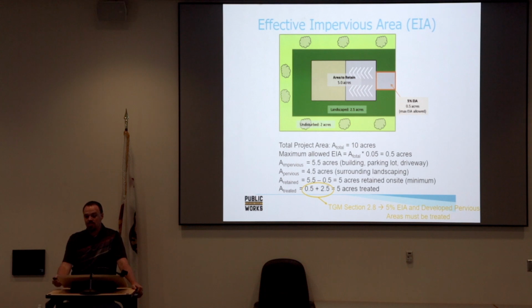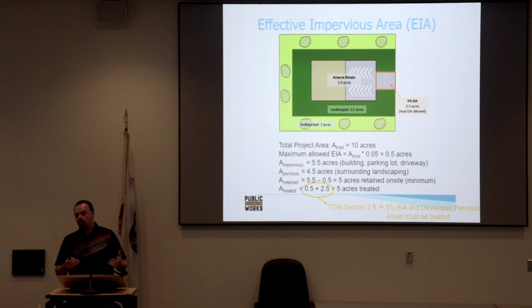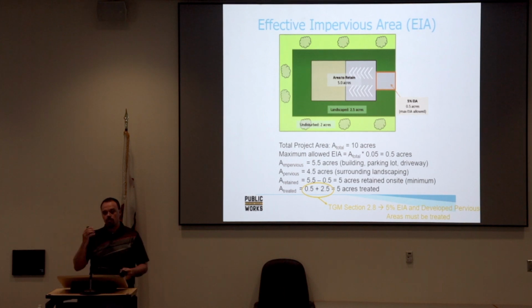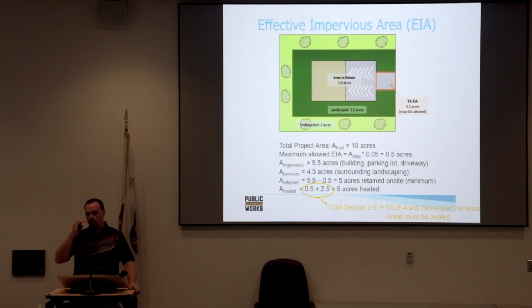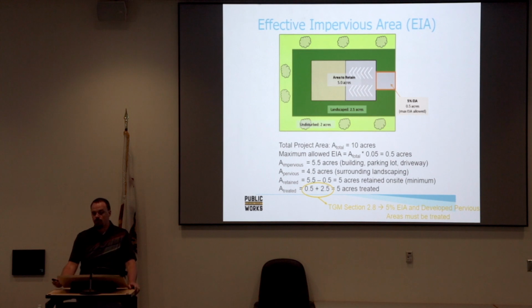In lots of instances, this isn't possible. It's pretty difficult to take this site, for example, if it's elevated above the street it's draining to in all directions. How are you going to treat that water? You're going to have to do some sort of work with your grading, put some sort of site perimeter berm around it to bring it down to treat it. It can be very difficult in some areas to do that. So again, that's where discretion comes in. We've got to make sure that to our satisfaction...